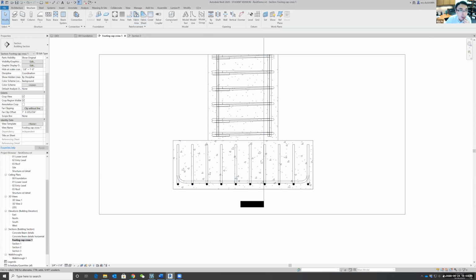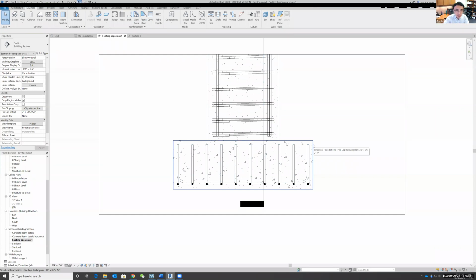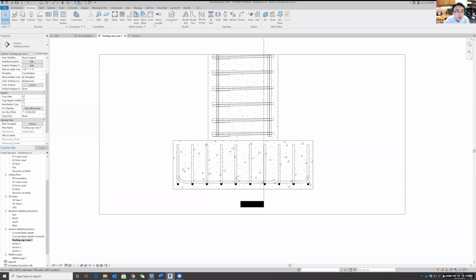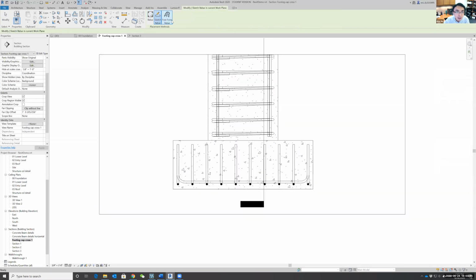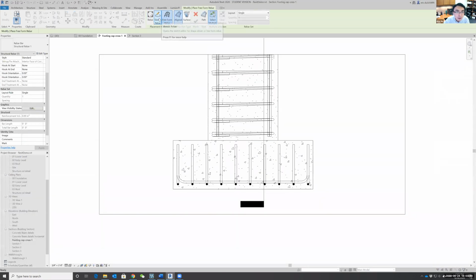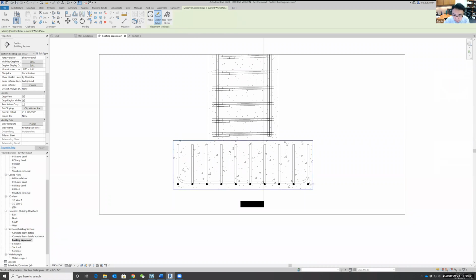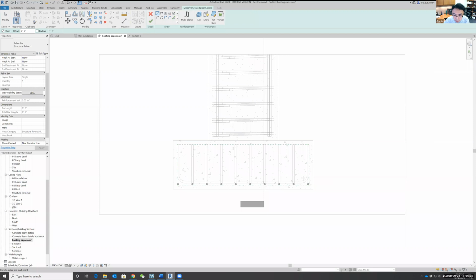No. Okay, so guys, I'm having this issue similar to what we had before. The rebar must go inside this foot, so I need to make sure that this is the work plan I'm plotting the free sketch rebar. I had this issue before. Let me see, current work plan, sketch rebar. Yeah, it should be this one. Okay. All right, and then click OK.